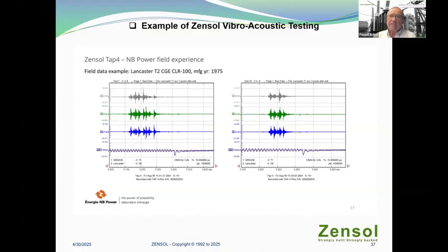And if it's not synchronized, your tap changer could be in serious trouble. So, yeah, it's not related to the DGA. As I've mentioned in other forums, maybe half of all transformer failures are tap changer failures, correct? Yes, exactly. A large amount. And it's a mechanical issue.